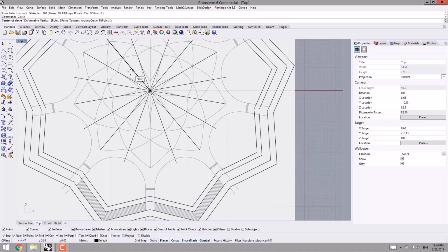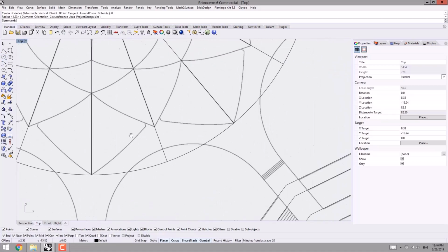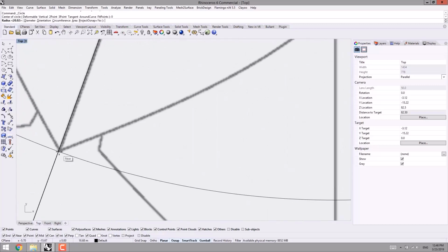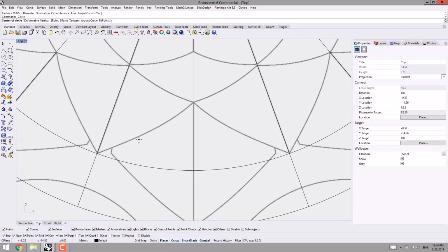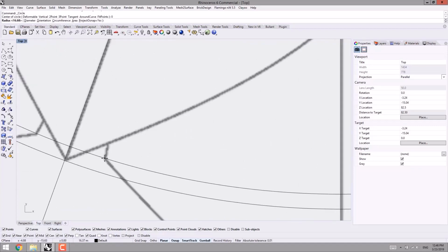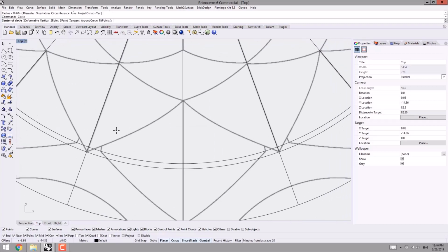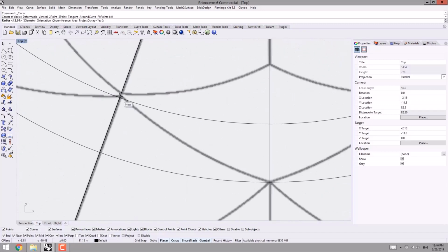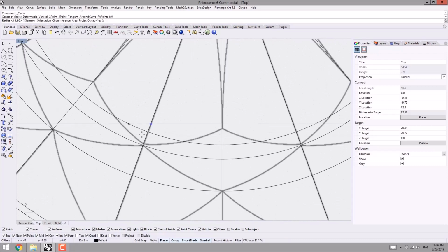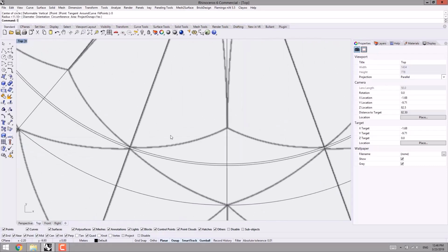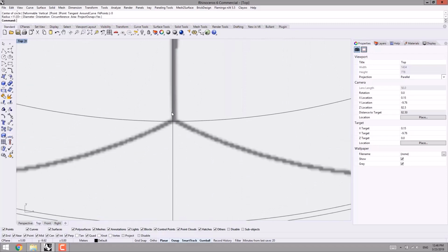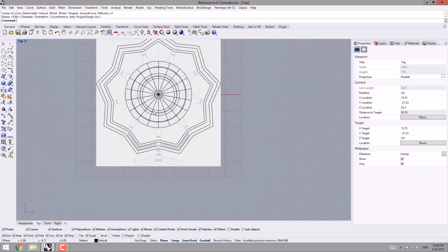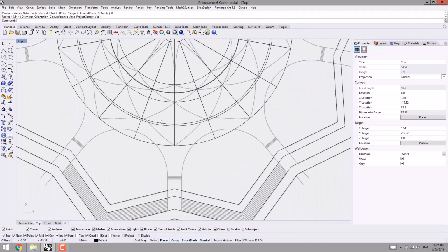And even here I can create a circle at the origin point like this. I press enter, one more till this part, the intersection, and then the next one I create another circle this way at the corners or intersections. So we can use these circles for sketching other parts of the model, for example this way, and then one more. Very well. And then the last one which touches the intersections this way.